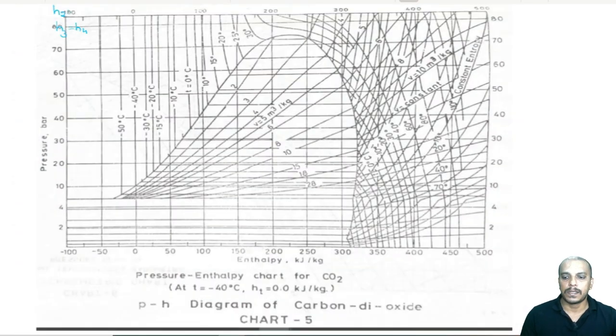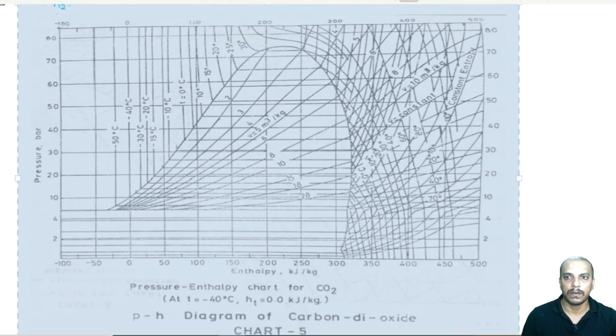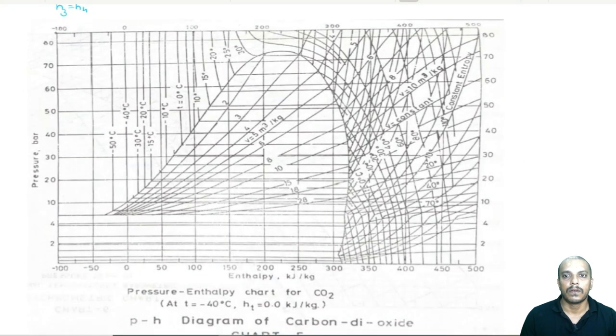Now, the 25 degrees Celsius line goes like this from here; outside the vapor dome the constant temperature line goes like this, then within the vapor dome pressure and temperature both remain constant, and if you want to go beyond this, it has to follow this constant line, alright. So, that is the 25 degrees Celsius line.